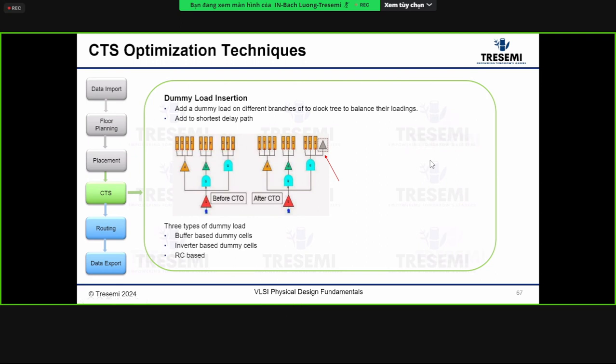Ngô Thanh Hảo says handling wires. That is correct. So what you do here, instead of adding a buffer, is add wire antenna, wires going in different directions, right? Up here, sideways, whichever you have tracks for. That is the RC-based. So basically, you're adding capacitance loading onto this to slow down this net. Great, Thanh Hảo. That's what RC loading means: you add wire instead of buffers or inverters. You add just wires to load down this buffer, so as to slow down this particular branch.